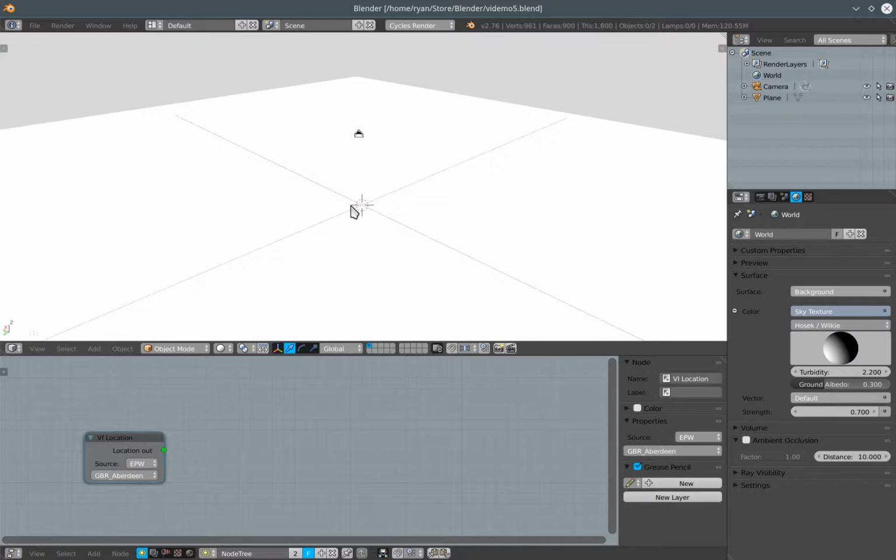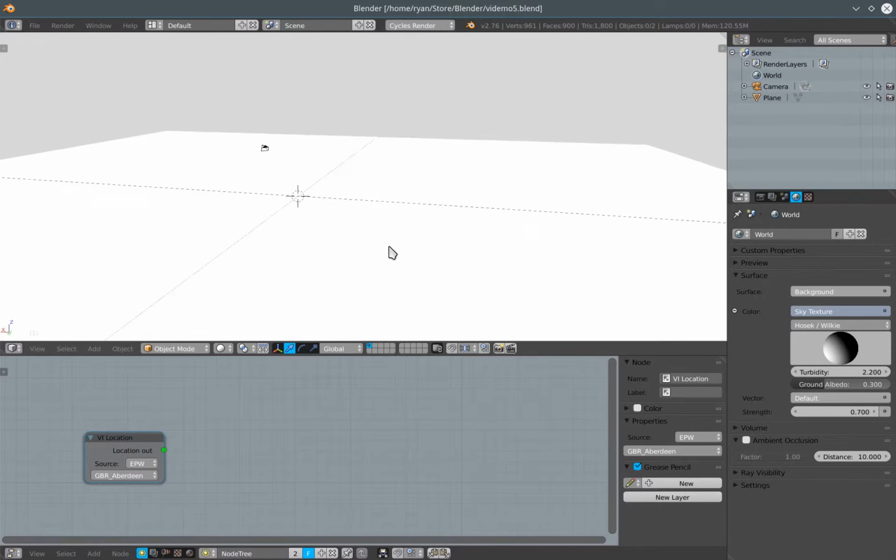of the vSuite. The LiVi component of the vSuite uses a program called Radiance, which is a very popular and pretty accurate lighting simulation engine. It uses Radiance in the background to allow us to calculate things like lux and daylight factor and useful daylight illuminance, etc. So I'm just going to run through very quickly how to do a lighting analysis with LiVi.